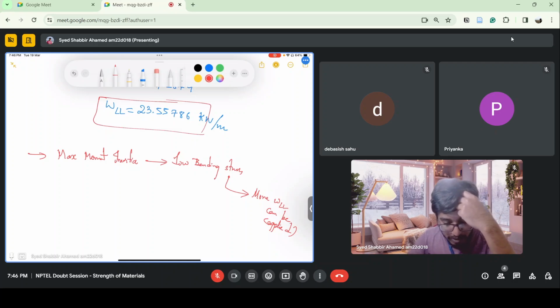So given a material, the flexural rigidity in beam analysis increases when the material is placed farther away from the centroid of the cross section. So we have seen this. In the box section, the centroid is present, but the material is far away from the centroid.